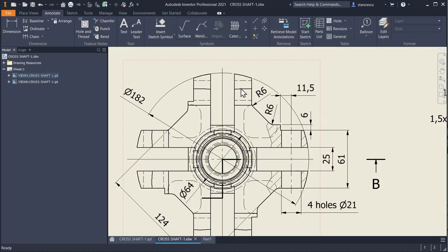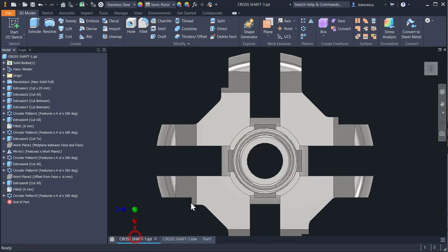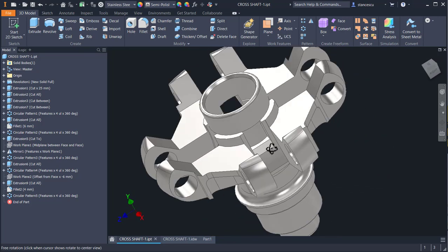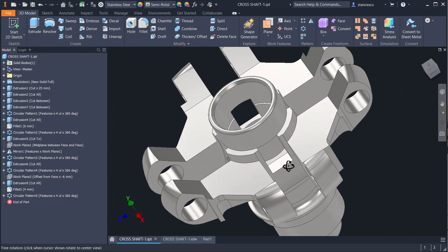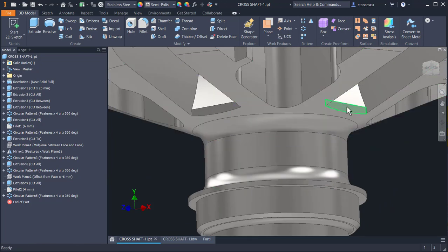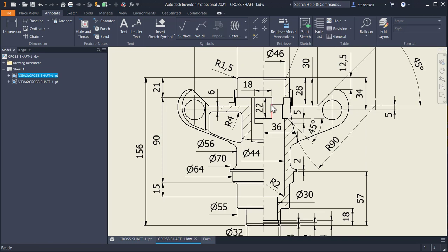Next are these cuts here, rectangular cuts, you see, which are better presented on the real part. You see, cut here, which have some chamfers. This is one, on the width of the cut, and there is another one here on the thickness of the other cut. Yes, let's create a rectangle 18 on 22 placed at 21 from the top and centered on the center point.